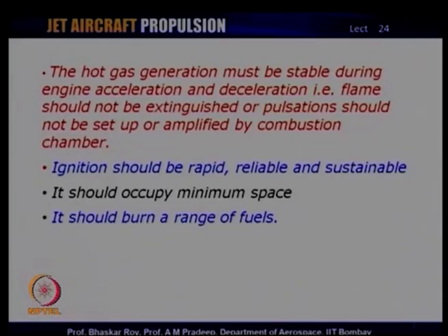Now, these are distinct possibilities. These can happen during the combustion chamber operation, and the combustion chamber designer must ensure that none of these things happen during the operation of the engine, because as I mentioned, these are realistic possibilities. Flame can get extinguished, pulsations can occur, and some of the disturbances that are occurring can get amplified, and if those things happen, it would be absolute catastrophe.